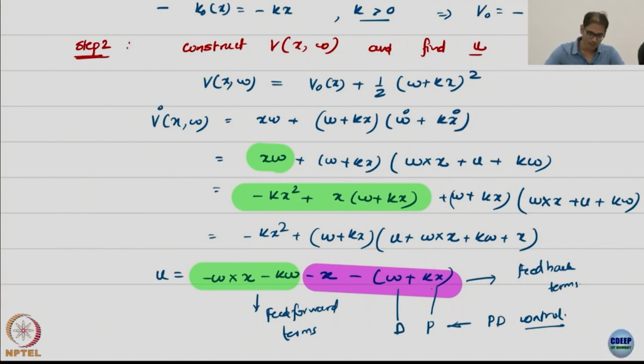Alright. A lot of people also wonder why PID works a lot of times. It's a big question, right? Why does it work all the time, and why do we do all this nonlinear design if PID works so well? Typically PID will work well when you don't know the feed forward terms very well. By the way, PID works only in the linear domain, actually it does not work in the nonlinear domain. If your oscillations are too big, then it will not work well for you. So what you try to do is maintain the system in a very linear zone and then you apply the PID, and it works well.